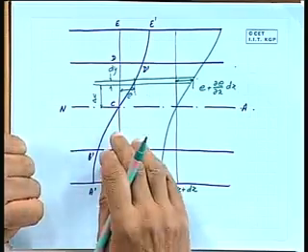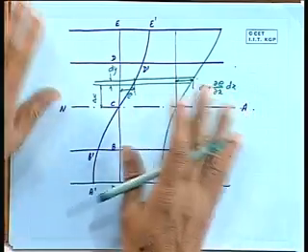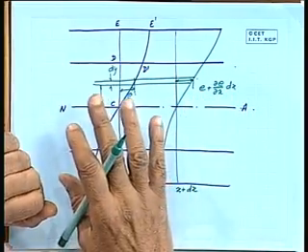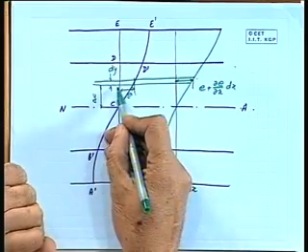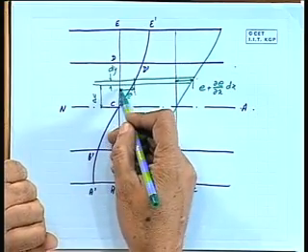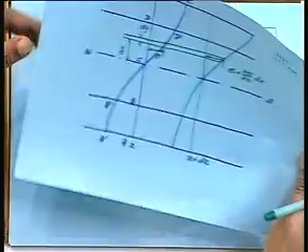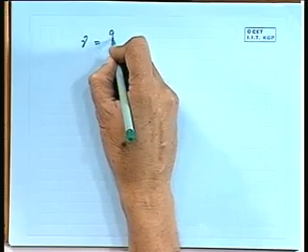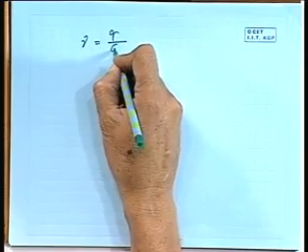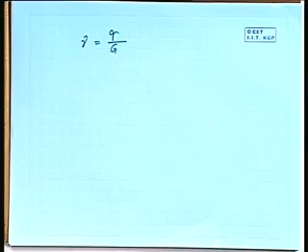Now, because of the shear force this happens and therefore, there will be a shearing strain. At this layer, at this position, we say that there is a shear stress. So, if there is a shear stress, then what is the shearing strain? We say that gamma is the shearing strain, which will be given by the shear stress divided by the modulus of rigidity G.